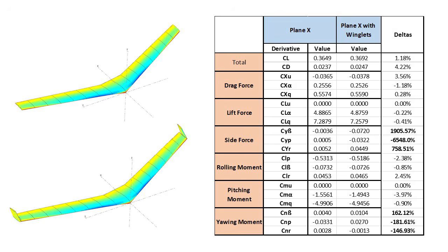Now, to get a bit more practical, I made a super quick 10-minute single iteration flying wing design with and without winglets, and ran them through a panel method VLM analysis. In this case, XFLR5, because I didn't have much time to get a proper AVL or semi-empirical model running. Now, let's take a look at the non-dimensional stability derivatives and see if their values agree with the definitions we just reviewed, which would then imply that the plane is stable.